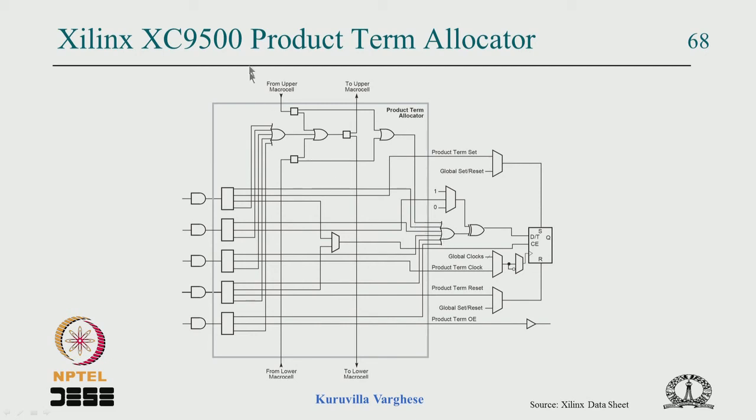So you can cascade the previous AND gates through an OR gate right down here. If you have more than one product term and this goes through, you can see that it gets combined there. If you look at this section, these 5 product terms can be combined with the previous one, the top one and the bottom one.